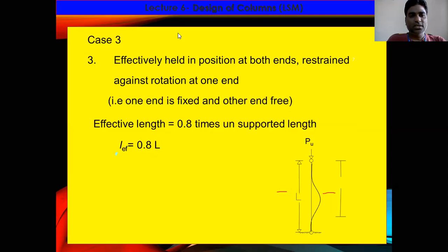Now coming to case 3, that is, effectively held in position at both ends, restrained against rotation at one end. That means one end is fixed and the other end is hinged. I cannot say it is free; it is hinged, because it is restrained against rotation at one end only, and both ends are held in position.